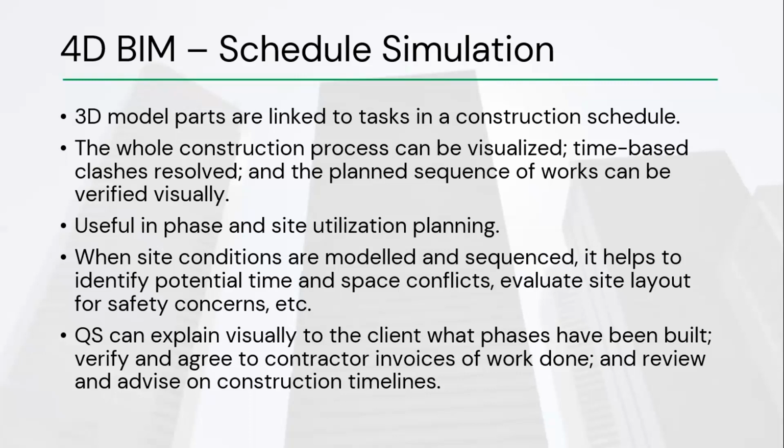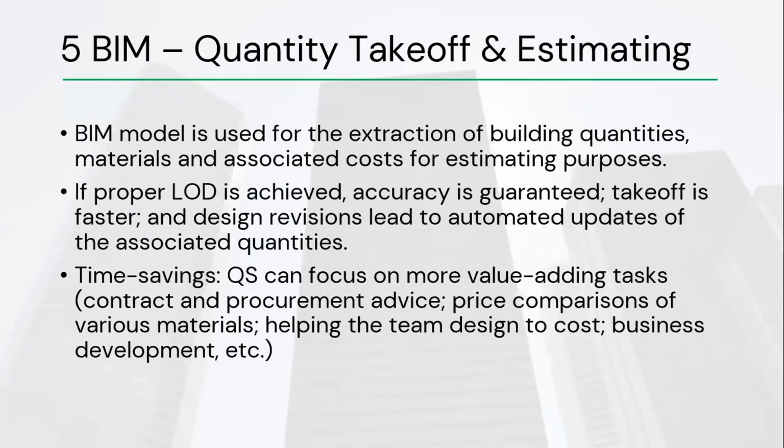And then let's look at 5D. And 5D is the use of BIM in quantity takeoff and estimating. In this case, this is where the quantity surveyor plays a very central role, because it involves the use of the developed model to extract quantities of materials and associated costs for cost estimating purposes.